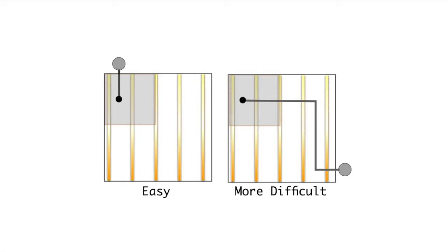A wet room can also be constructed on a raised deck built on top of the original floor. However, it is best to plan for the waste pipe to be running parallel to the joists and reasonably close to an existing soil pipe. In order to plan this properly, it is necessary as a first step to check the direction and position of joists and the location of the soil pipe.